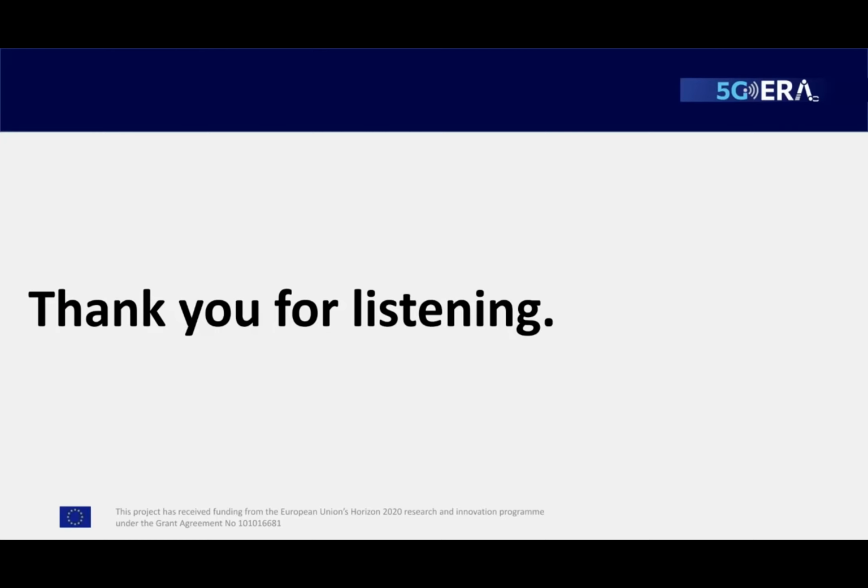Thank you, Michal. Another question is, ROS communication, like SLAM, requires multiple topics to be considered at the same time. So the question is, how can we convert the ROS communication into the REST communication that is used by the 5G ERA reference network applications? Yes. Well, for the data from the camera, there are methods for sending this data available on the client, which will automatically compress the data into JPEG format and send it to the network application.